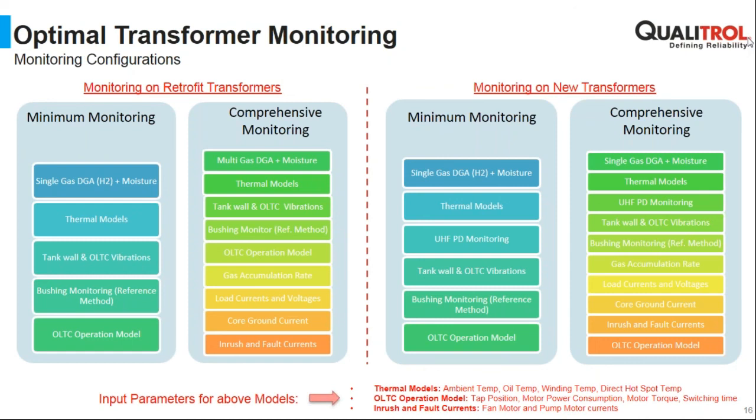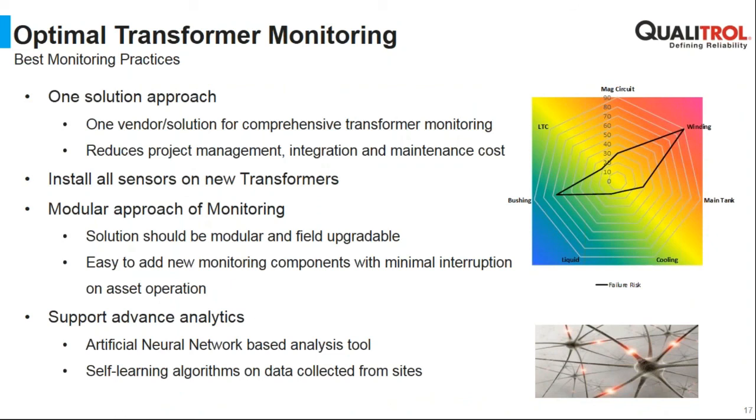Yeah, I mean, talking about the possibilities, usually these transients are creating insulation failures, and over time, when they are loaded with these transients coming in very rapidly, most likely it will create insulation failures, which might be able to be detected. I think there is some research going on on that. It could be a good possibility also to detect by partial discharge, once the insulation is kind of infected.